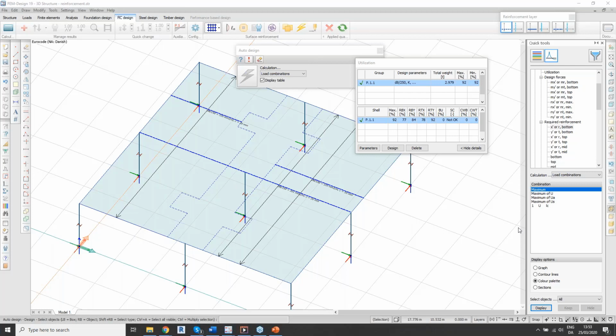That is one thing. And another thing is that the punching shear reinforcement, that's something different. So, yes, it was made as an educational example. It's not a real life project. But as I said, if you face that in a real life project, you just increase the thickness of your plate. Yeah, thank you.